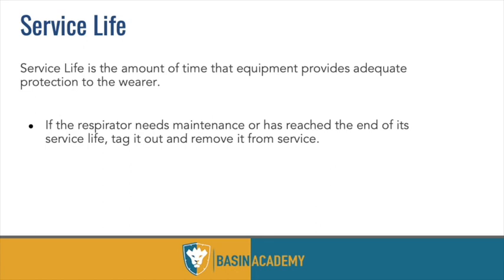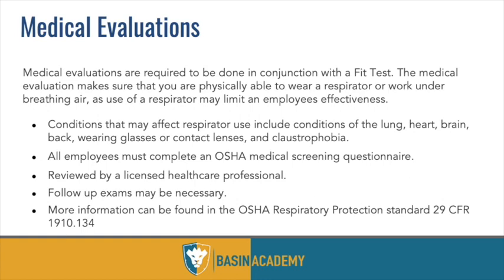So the service life of respirators changes based on manufacturer, use, wear, and tear. Was it dropped, kicked, booted across the yard? What do we do with this thing? All that's going to determine service life. So there's the minimum and the maximum, and that's going to be stamped typically on the respirator or with the purchase documents as well. Medical evaluations, I already mentioned these.